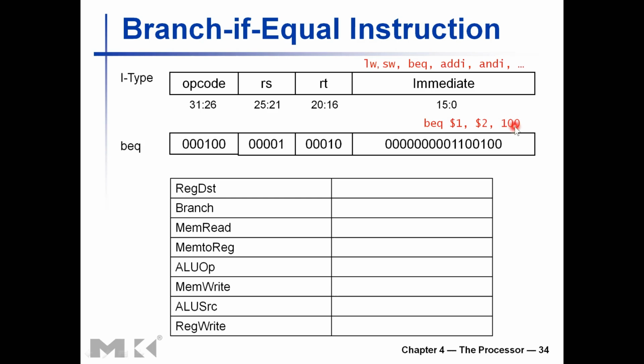How many instructions you need to jump forward in order to reach where that label is put. So that is the task of the assembler, to get the instruction sequence for the program counter value that should be here, which number of instruction in the sequence of execution the current instruction is, the next instruction is.